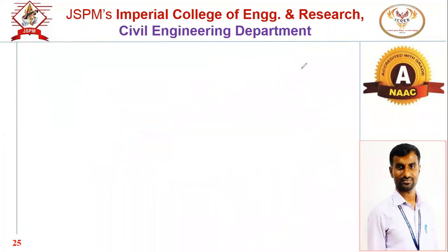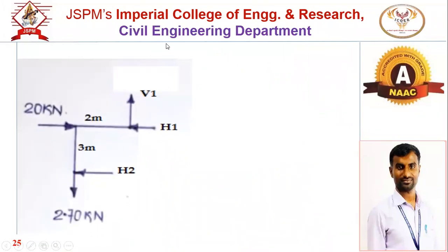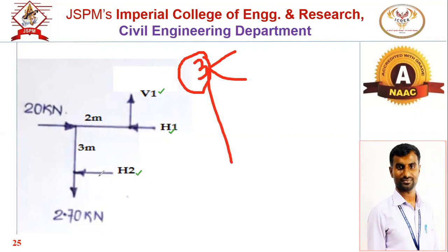Now in the cantilever method, if this is the fbd of the cantilever method, what is the change? So in case of the cantilever method, here one force is vertical which is unknown and two horizontal forces we have to find out. Okay, here definitely three forces are unknown also. In the cantilever method also three forces are unknown. So we have to use three conditions. Out of three forces which are unknown, one is vertical and two are horizontal.